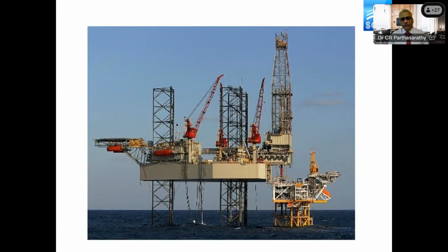So what is the geotechnical challenge for this condition? The geotechnical challenge for the jack-up rig is to assess the leg penetration analysis and the potential hazards that it will undergo during the leg penetration. For example, the punch through, I will discuss that in a bit. And also when this jack-up rig comes next to the platform, it forms a huge crater around the spud cans that will disturb the soil zone around it.